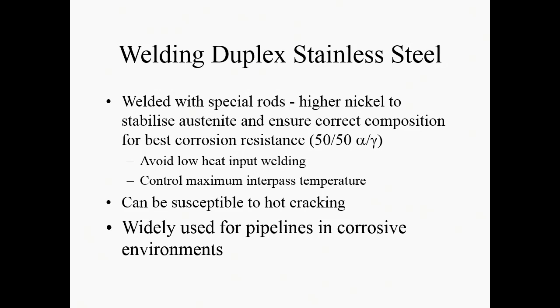And hot cracking can occur if you put too much heat in, so that's controlling the amount of heat that you want to put in. Saying that, it's all about control. It's not impossible to weld duplex steels. It's quite straightforward if you've got the right level of control in your process. And that's why they're widely used for pipelines. Generally, that short distance from the wellhead to the first processing step, or the first distribution step, where you get high pressure, highly corrosive systems before you've dropped the pressure down for transport, that's where you would put these types of materials.